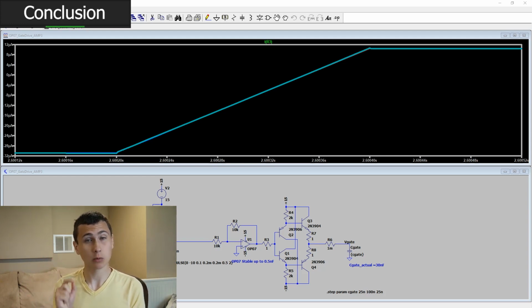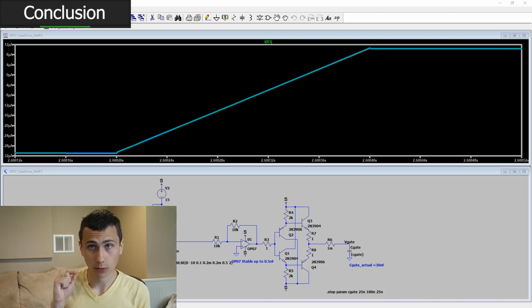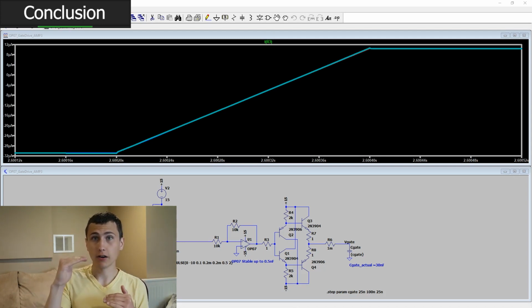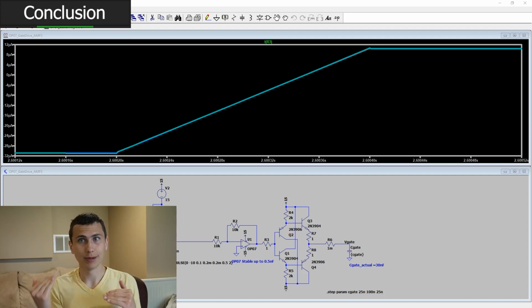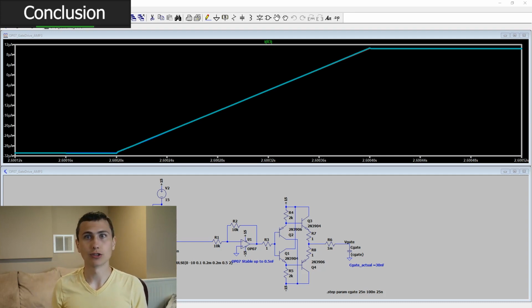And that means that there will very, very likely be a DC offset between the input and the output of this voltage follower. Highly probable, in fact. But for our system, since we have the compensator, it doesn't really matter. Right? A fixed DC offset will be accounted for by the integrator. That'll just crush it, right?